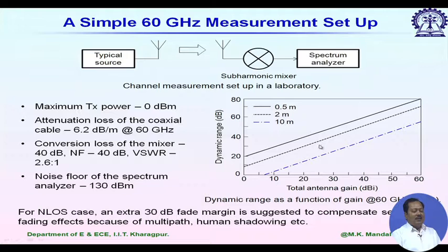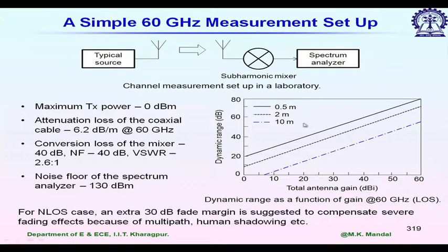Maximum power is limited by the non-linearity of the device. When we design any system, it can be a microwave system or millimeter wave system, even a low frequency amplifier, we consider it as a linear device. That is why for a low frequency amplifier we sometimes say small signal equivalent circuit or small signal amplifier. Now, if I increase the input power, it can move to its non-linear region, and then we have to model it in different ways, and it will be associated with other high frequency components. So, maximum power would be limited by the non-linearity of the devices being used in the system.